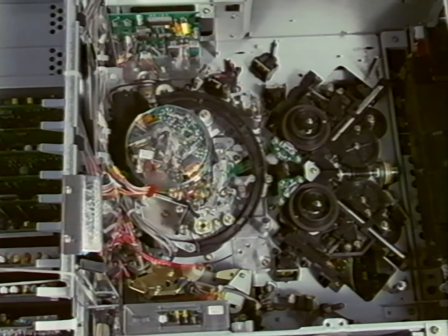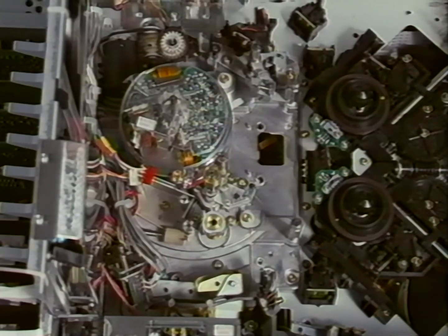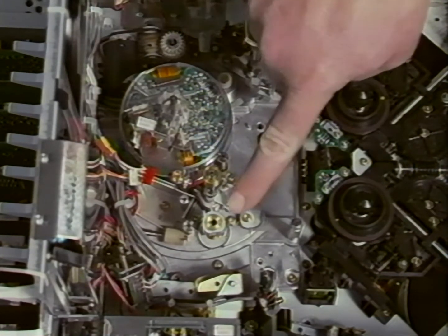Replacement of the capstan motor. This first view shows the capstan with the threading ring intact. All three of the fixing screws can be reached with the threading ring remaining in the machine. Only the pinch solenoid block would have to be removed before you could remove the capstan.